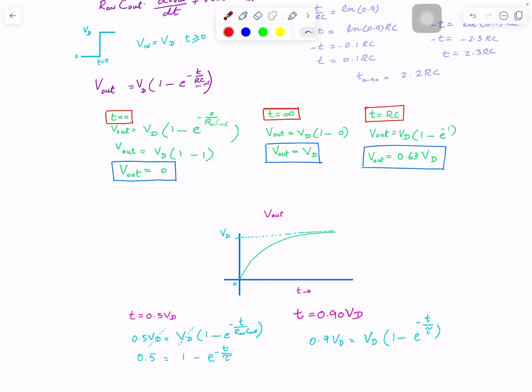So what we really want to understand is when this waveform from 0 to 1 reaches 50% of its final value, which is VDD, the supply voltage, so 50% somewhere here. The time we really want to figure out is the time it needs for this signal to reach 50% of VDD. And that is really kind of a delay here.